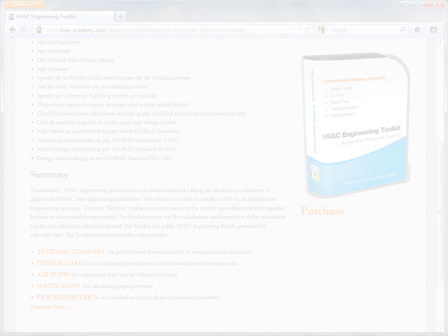Unit shall include mixing outdoor and return air dampers to provide the building with fresh air, heating coil, cooling coil, and an electric humidifier to maintain the conditions of supply airflow at point A with the temperature and humidity preset sufficiently low to assimilate the heat and moisture from the building throughout the year.